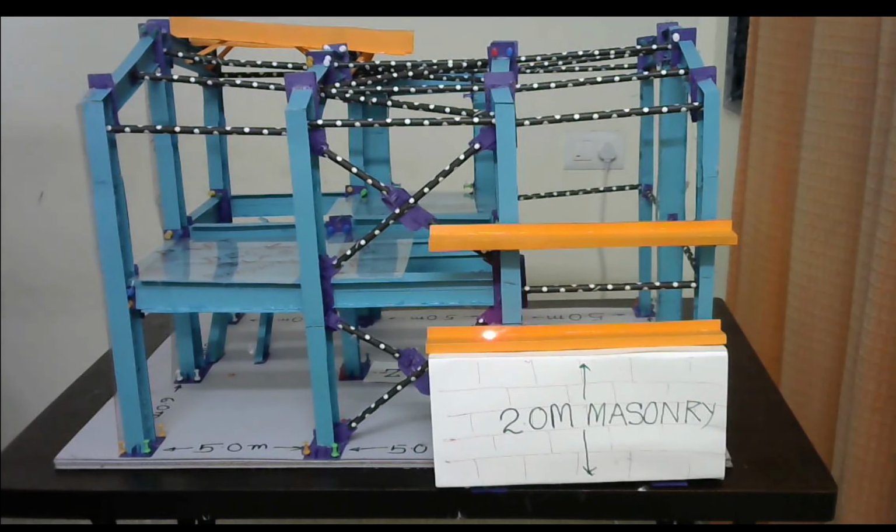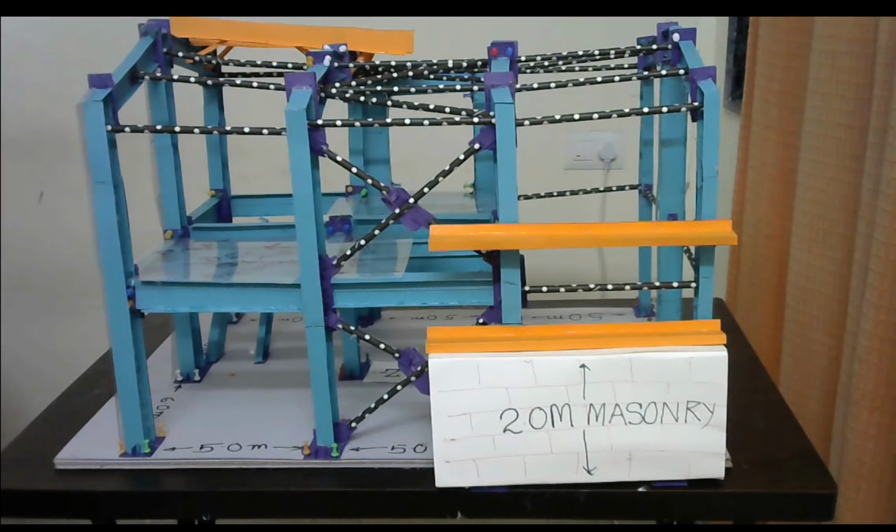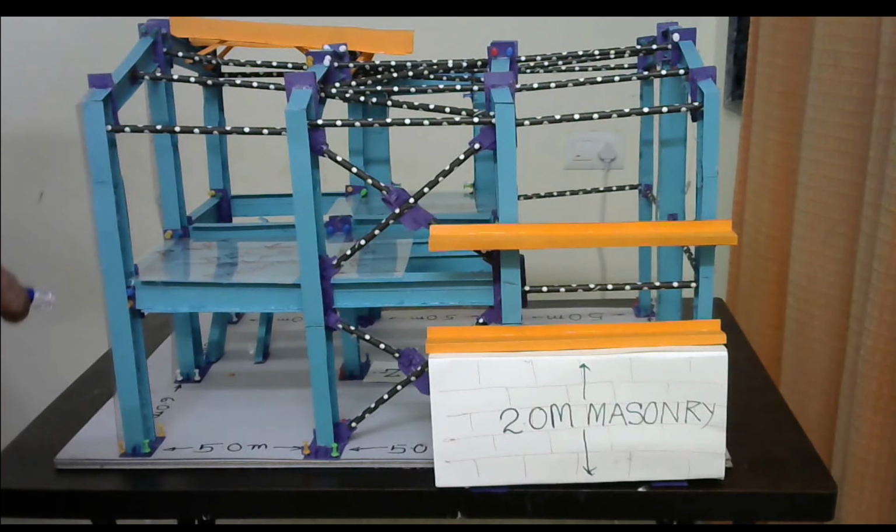So suppose these girts are provided at 1.5 meter center to center. For these girts I have shown only the partial girts. So these girts could be here up to this point, then here, then there will be a girt. So if they are at 1.5 meters, LX and LY will be 1.5 meter. But see now, there is a 2 meter brick wall below. So for the first 2 meter, LX and LY will be 2 meter. But thereafter the LX and LY will be 1.5 meter. But LZ parameter will remain as I have already discussed.